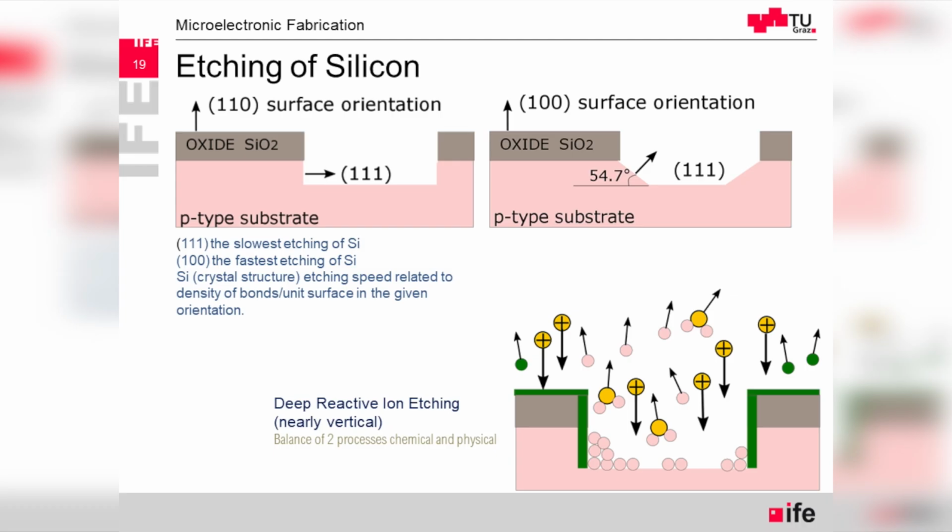So that goes through the silicon if we want to connect two dies without external bond wires, but with bump at the bottom, so to have very dense interconnection. This is, for example, done. And for that, we need to have a ratio of, like the via should be as narrow as possible, because then we have lower capacitance, less parasitics, and also less area that it consumes. It's really difficult to make something that is narrow and deep. So there are also some limits to that. That's one other challenge that it's also interesting to point out.